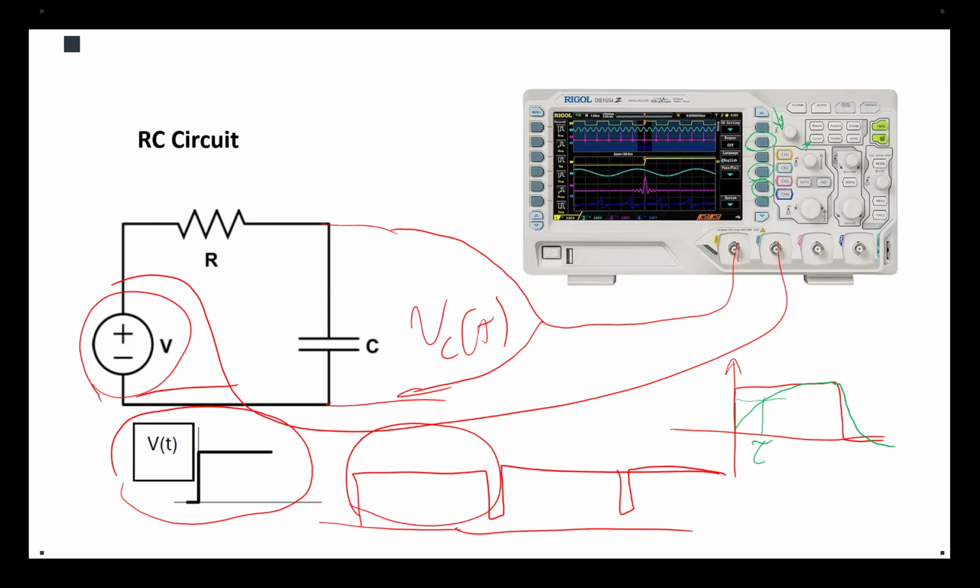Now, my suggestion for you is to use both A cursors as the reference, because you can see the time 0 in the oscilloscope. Okay, so choose the vertical cursor A, let me use another color, and set it at the time that your change is started. So time 0 in your calculation. Are we good? So this is the vertical A.